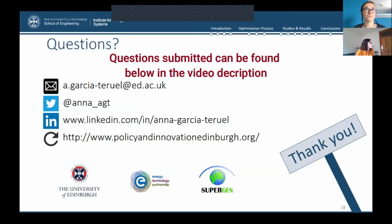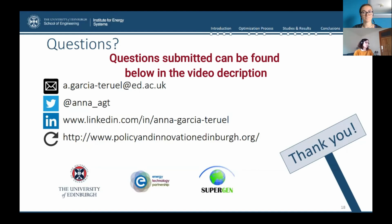Our next question is from Phil, asking, does this optimization of float design apply omnidirectionally, or does it demand a single wave direction? Yeah, that's a good question. So the shapes that I showed were optimized assuming a single wave direction, but the method can be applied for multi-directional seas. For example, in the work I have done with the wave energy developer, we used this method taking into account multi-directional seas. So the results I generated and showed here are for a single wave direction, but it can be used for multi-directional seas as well.